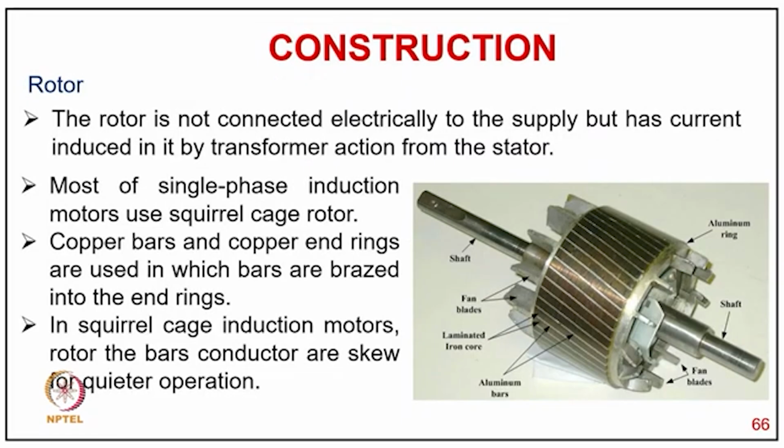Then you have a rotor, the cage bar with the aluminum bars and end ring made normally of aluminum with the skewing slots or skewing bars. The fan blades are on top. These blades are also part of the aluminum die casting, which we do together.